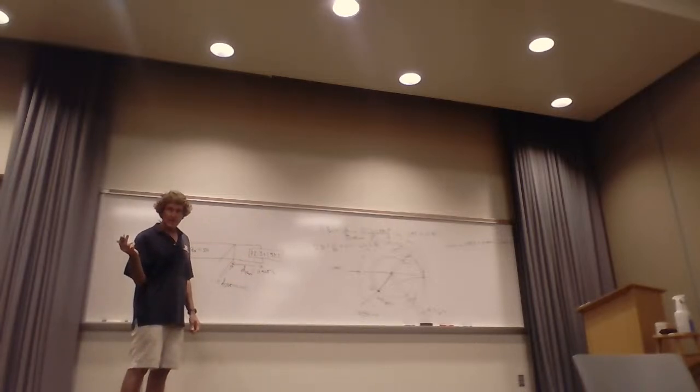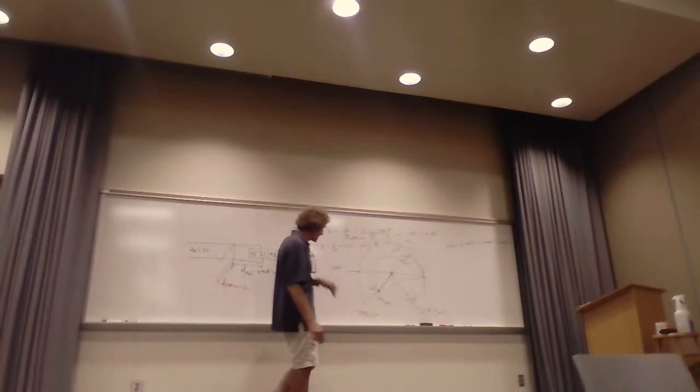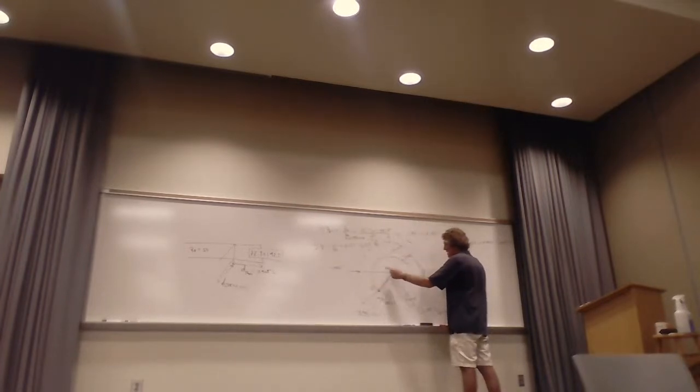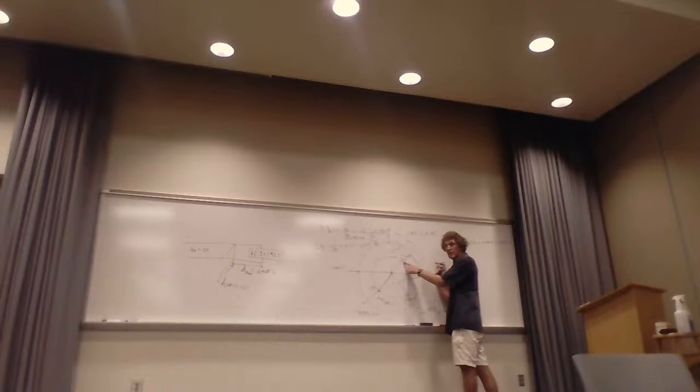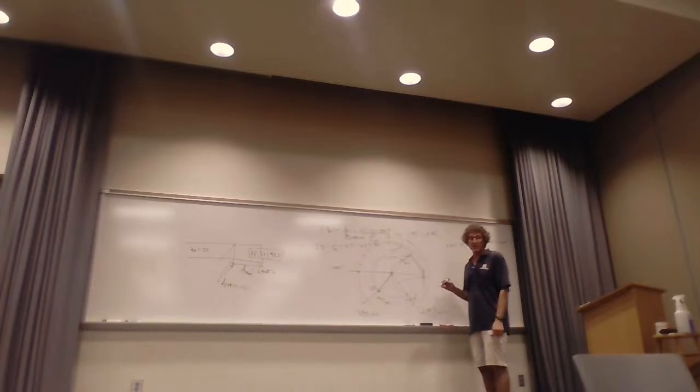I mean, this is one possible solution. It doesn't matter which one Wentworth chooses. Now, the other way to do it would be, instead of landing here, going from here to here, now we go from here to 1 plus j1.8, correct? And then you've got to get rid of the j1.8, which means you start there and you go all the way to minus j1.8, right, class? Do y'all follow me on this one? This is sort of a final exam kind of question.